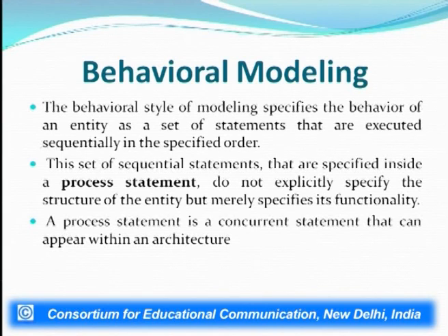And similar to data flow modeling, once we see the functionality, the structural description can also be deduced from it. The process statement, which is a distinguishing feature of behavioral modeling, is a concurrent statement that can appear within an architecture, and the block of statements contained within this process statement are sequential statements.